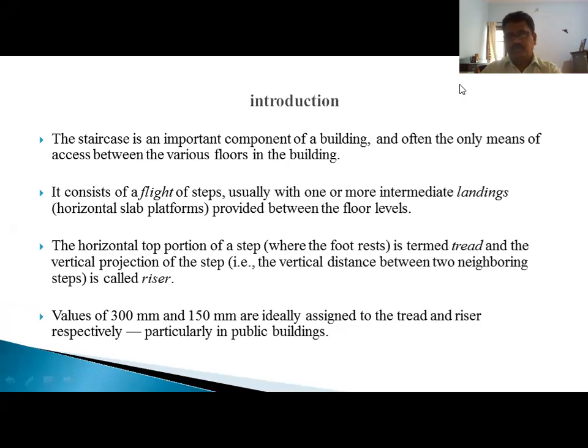What is a staircase? A staircase is an important component of the building, which provides connectivity between two floors. That means the connection between the two floors in the building. It consists of flights of steps, usually with one or more intermediate landings, a horizontal platform between the floors. The horizontal top portion is called the tread, and the vertical projection of the step is called the riser. These two are very important components in staircases.